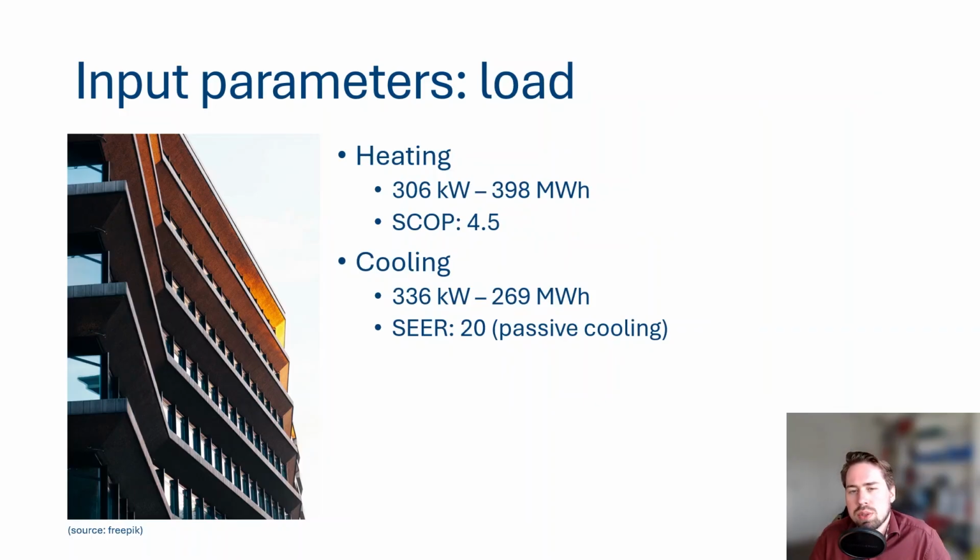300 kilowatts for heating with almost 400 megawatt hours per year in energy demand, and a COP of 4.5. In cooling we have a higher peak load of 336 kilowatts, but lower energy demand on a yearly basis, 269 megawatt hours, and we have an SEER of 20.